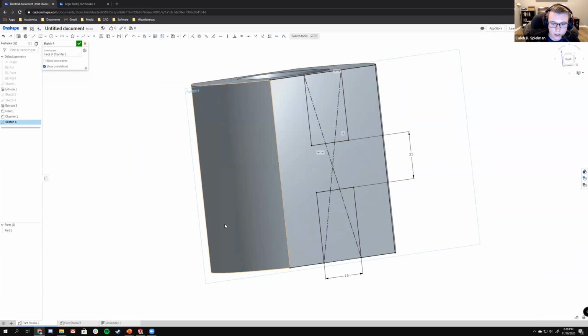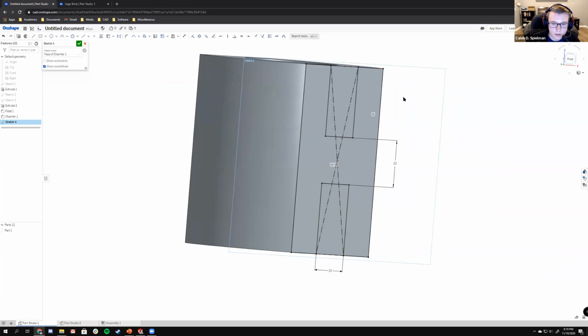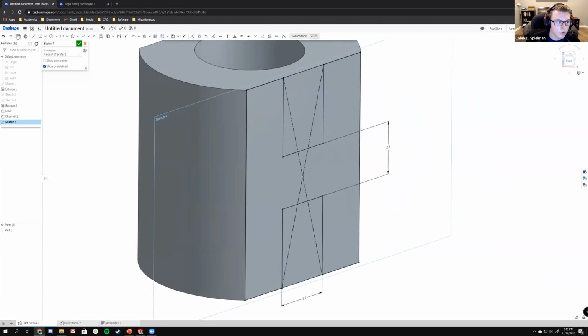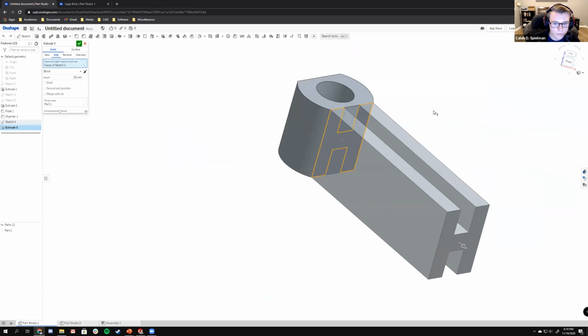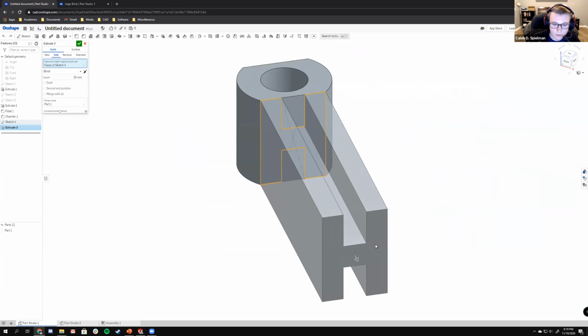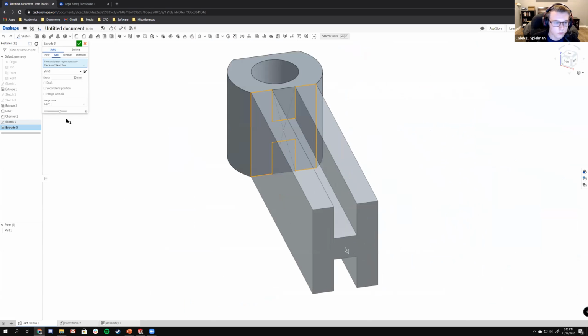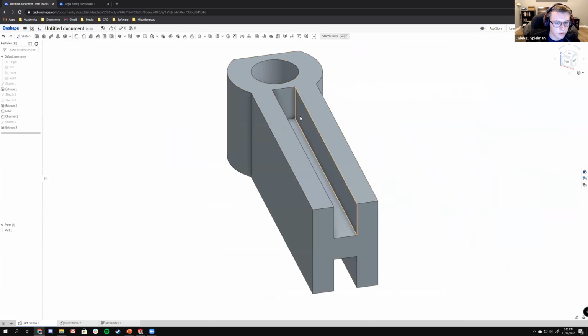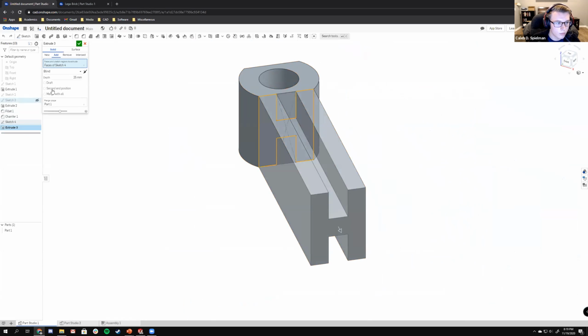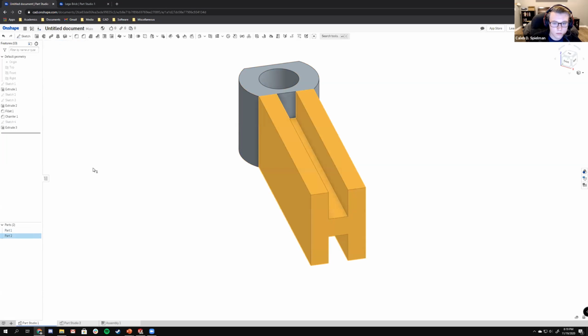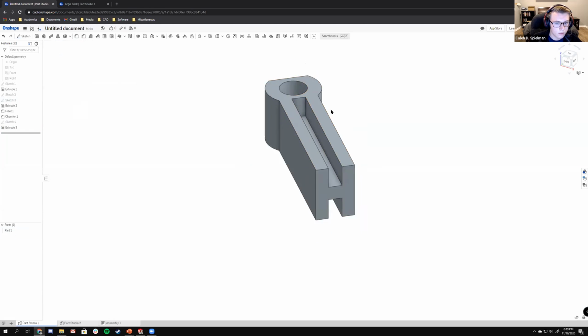So now I actually have a contour here. Of course, it doesn't highlight it because it's on the face, but I'm going to click Extrude. Notice how it kind of looks like an I-beam. Not really. But this is just going to be 25 millimeters. Again, for boss extrudes, top left, extrude, solid body this time. We're going to add, instead of new. Notice how new just makes another part, which we don't want. Let's just click add.